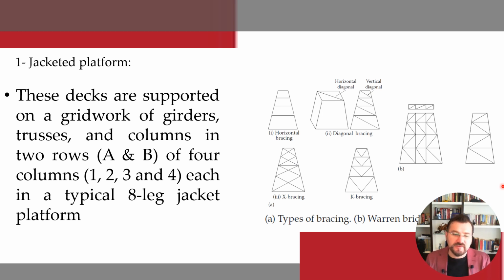The jacket legs vary in size, with large diameter corner legs and smaller diameter central legs, and are not actually vertical but battered, that is, they taper out from the top, so the base size becomes larger, giving the advantage of stability by resisting the environmentally induced overturning moment.